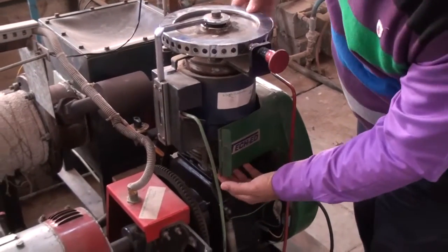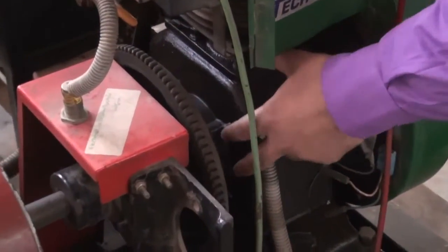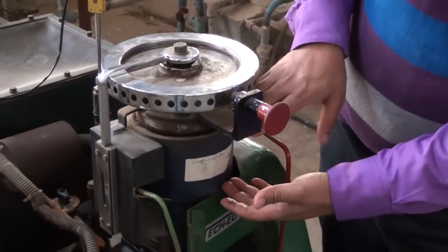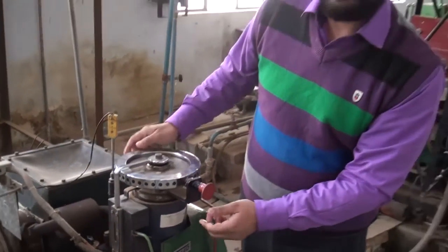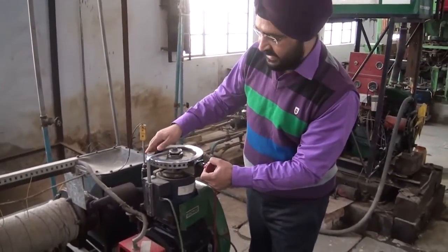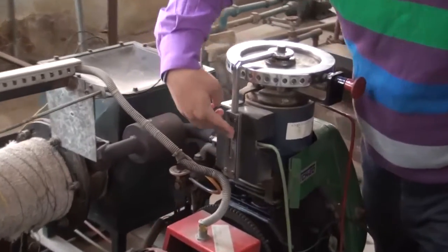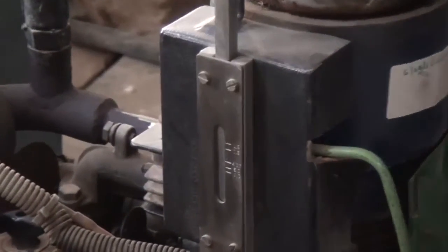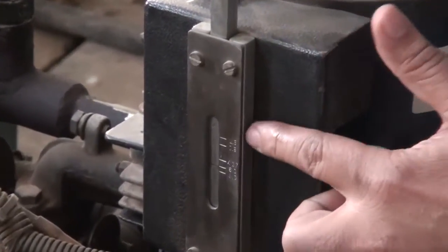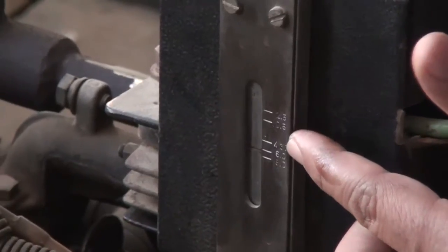At the bottom of that we have the main piston, and at the top of that we have the auxiliary piston. This is how we set the compression ratio, as it is a variable compression ratio engine. We just move this wheel and the compression ratio is set. On the extreme side you have the meter for the variable compression ratio. You see this calibrated reading, which varies from 2.5 to 8: there is a reading from 2.5, then 3.5, 4.67, then 6 and 8.